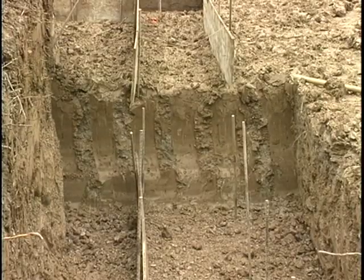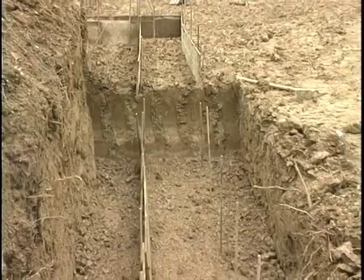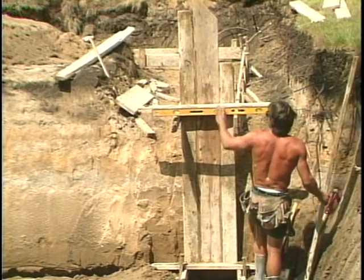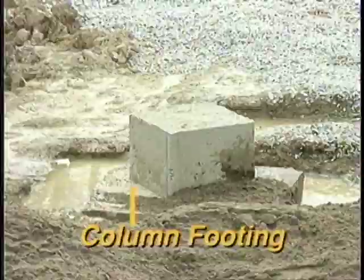Step footings are needed with a grade change or when called for in the plans. They will require some additional form work. Vertical blocking must be nailed or clamped to the form to contain the concrete until it sets.